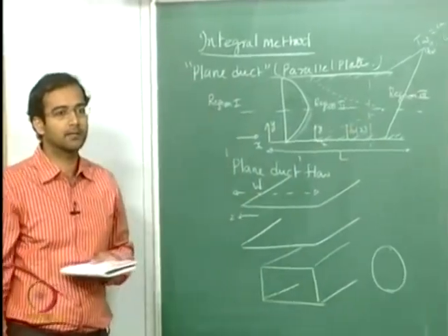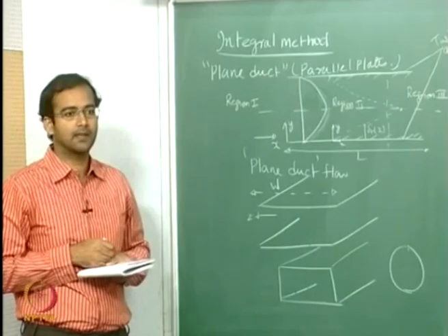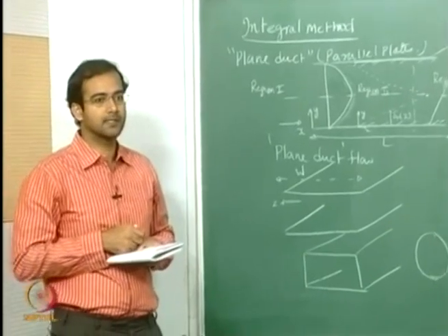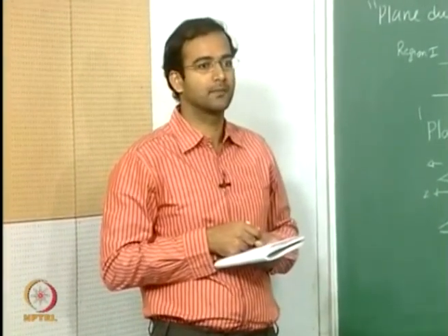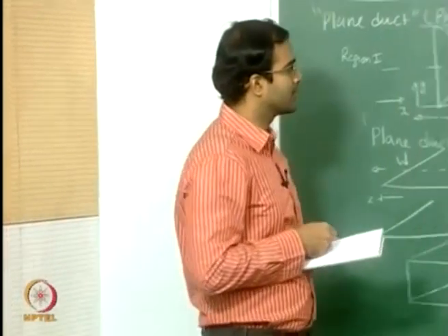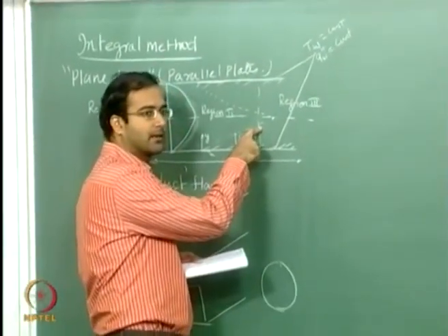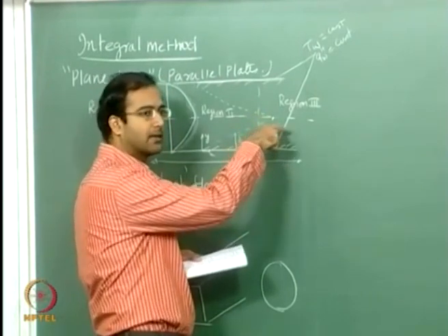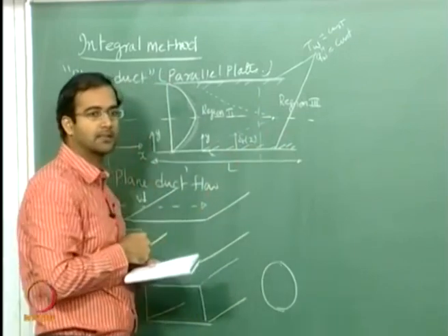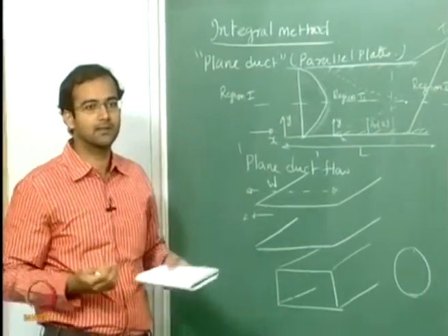The two boundary layers growing from the top and the bottom walls come close and then finally they are about to merge. In such a case, your boundary layer approximation will not be accurate. So you cannot therefore apply your momentum integral or your energy integral approximations in this region, and definitely your boundary layer equations are not valid once they fully merge, because there is no boundary layer, everywhere it is dominated